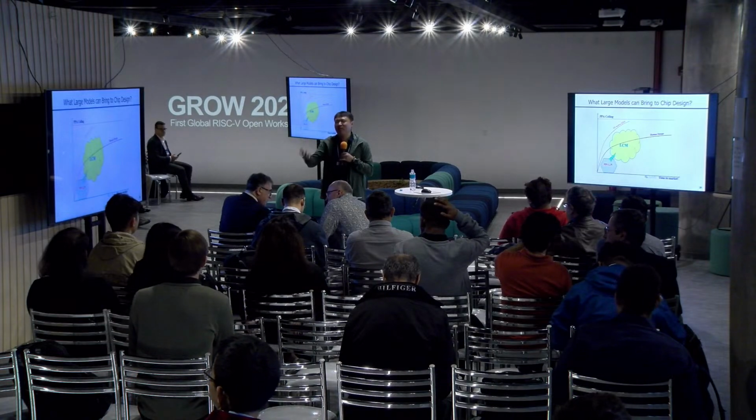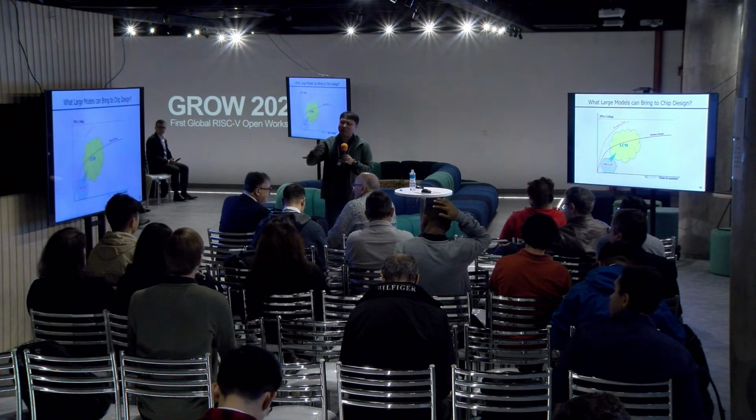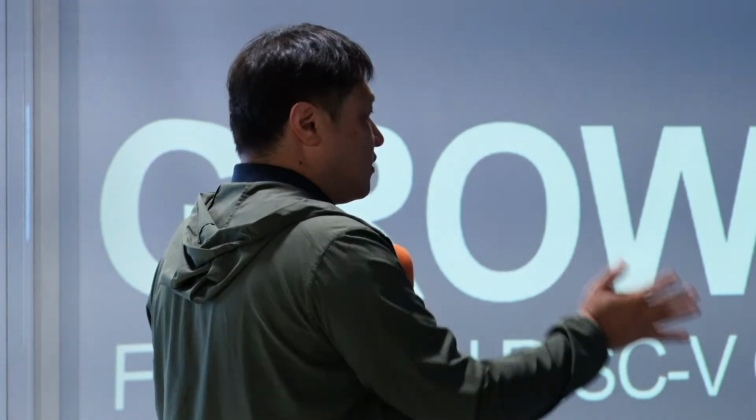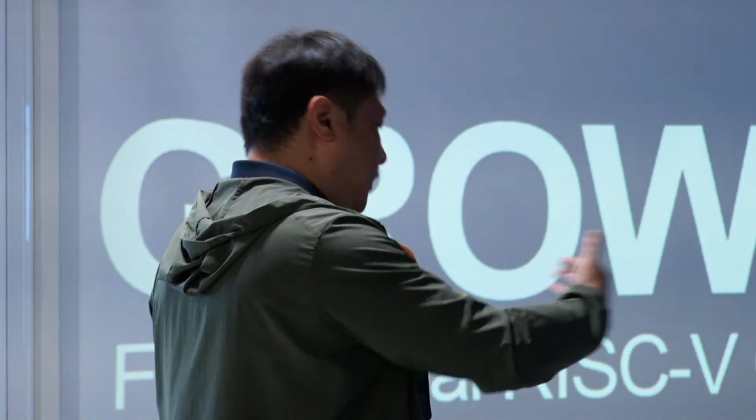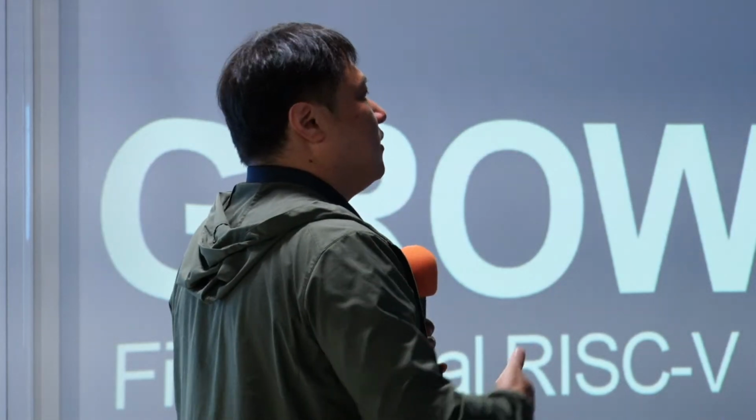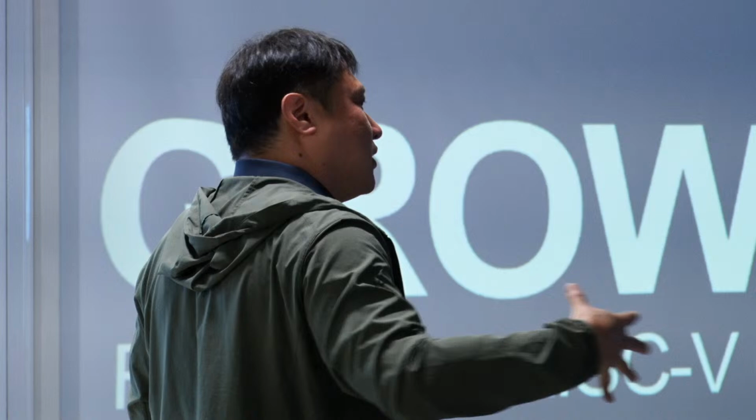But what we want to do is, we do it in several ways. One is we do augmentation. We have an RTL, and we can rewrite the RTL with the same functionality, but it's going to have different PPAC metrics. So from an initial RTL, we can automatically generate lots of other RTLs. Also, you do certain optimizations in the RTL, and again divide and conquer, to try to get a large code base.